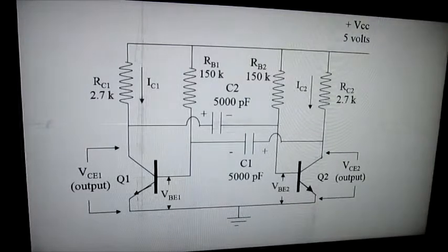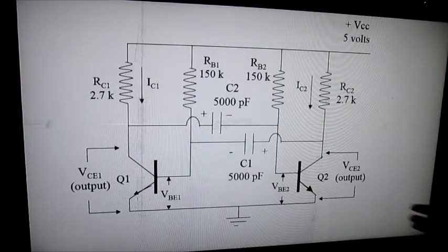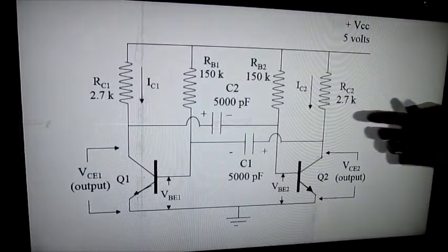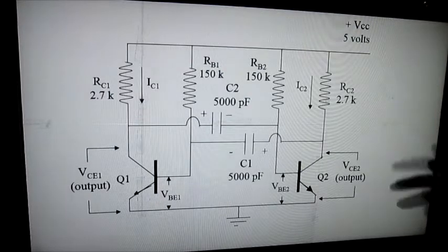Presented here is the circuit for the Astable Multivibrator. The Astable Multivibrator is a free-running multivibrator which has no stable states but has two quasi-stable states. The meaning of quasi-stable is that it seems, or apparently but not really, that the astable multivibrator has stable states, since its output would become high or low for a given time period.